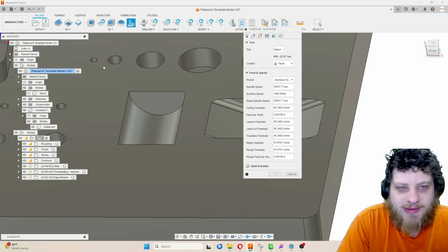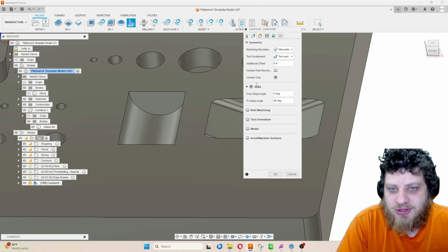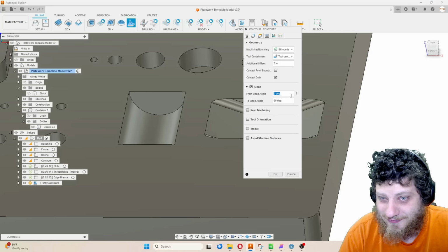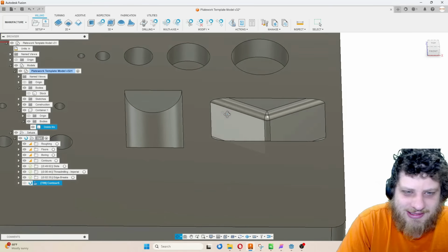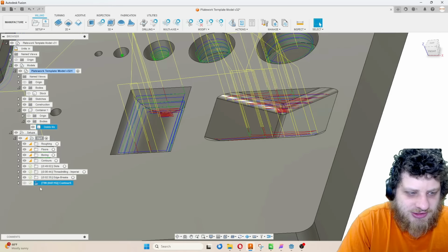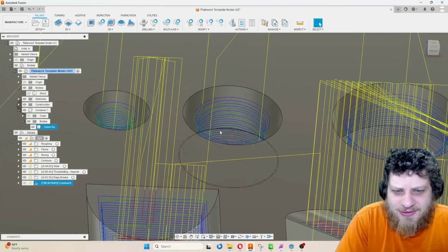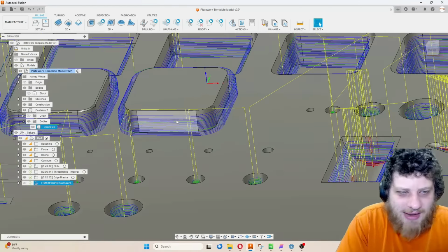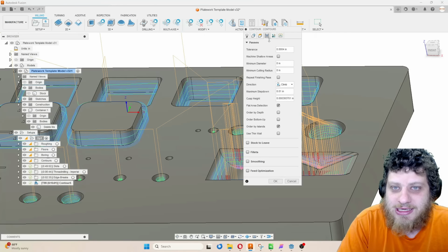Now, contour is one of my favorite surfacing toolpaths. It works best on steeper walls. So we're going to turn on the slope setting here, and we're going to go from, let's call it 45, that may be too shallow, to 90 degrees. And that'll get like the steep sections of the walls here while leaving the shallower sections. And let's go back and change our step down height. So as you can see with our current settings, the contour likes to pick up on vertical walls. That's not what I intended, because our vertical wall should already be finished with a regular 2D contour.